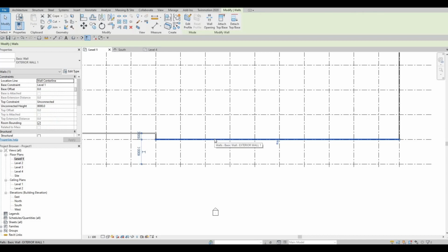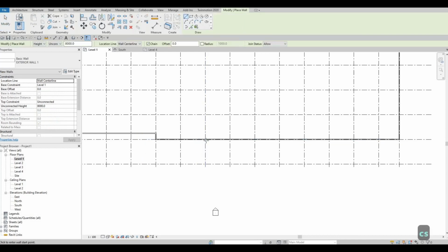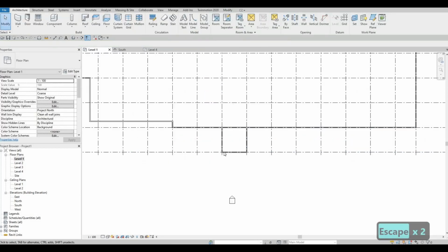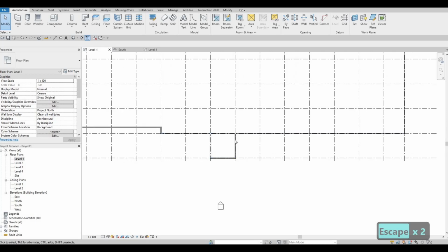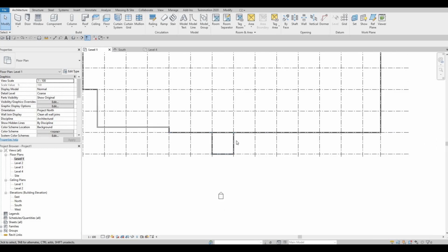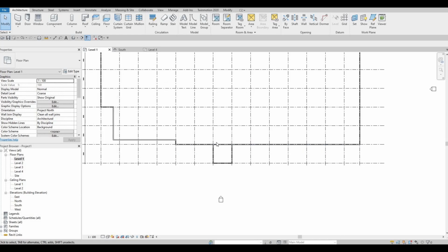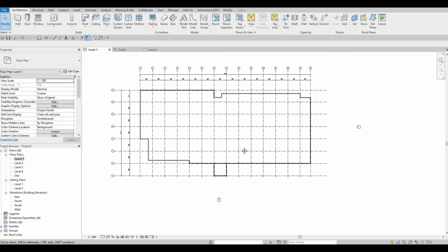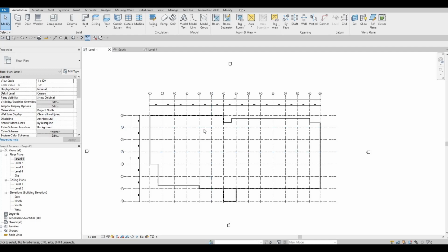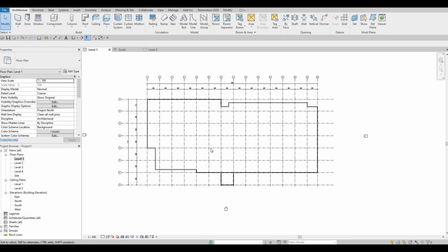And then here we're gonna click the exterior wall, CS, that's create similar. And then let's add in this. So we added our loading dock. So this is where our trucks will be entering, so that it could provide resources to our grocery store. We will have retail store here, the lobby for the condominium. So this will be a multi-use building.